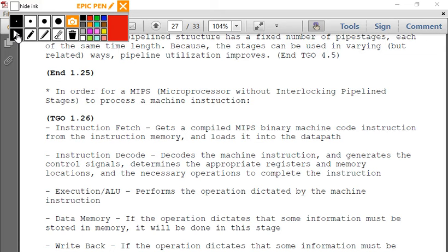And before, when you had the interlock stages, they all had to communicate with each other. Now you just use buffers between each one. Once you move the instruction to the registers, and you have a buffer between them, that means you can actually generate the next instruction. So because you have buffers between them, you can put up to 5 instructions in a datapath at once.